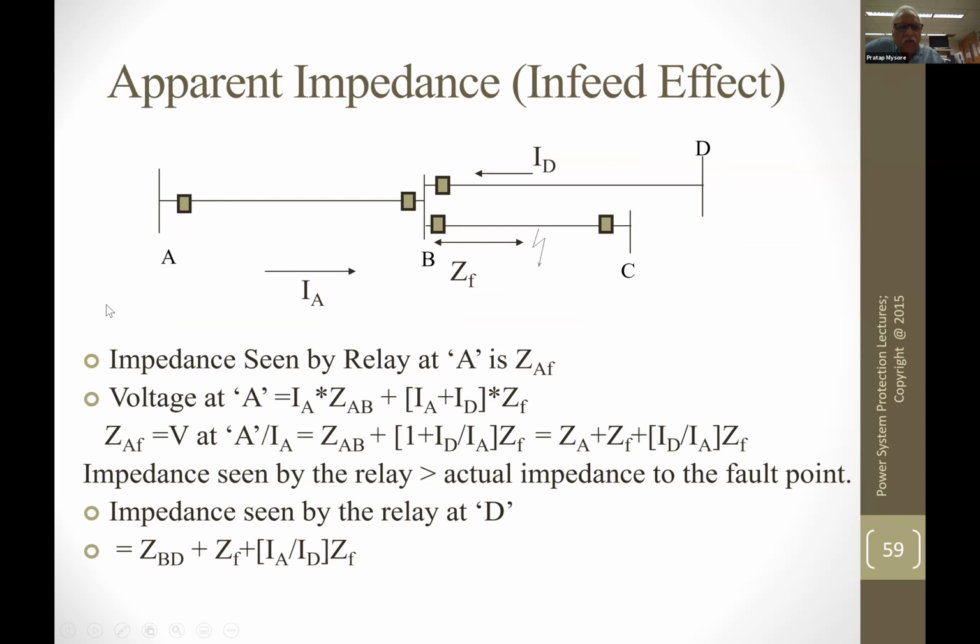If the load comes into the tripping characteristics, it will be seen as a three-phase fault, and the relay will trip. That is why we know that the load region is about 37 degrees, plus or minus, at 0.9 power factor. When you look at that, you try to cut off that portion. 0.85 is used sometimes, and then they chop the circular characteristics or whatever characteristics, so that if the phase relationship between voltage and current is less than 37 degrees, then you say it is a load, it's not a fault, and it has to be a three-phase condition.